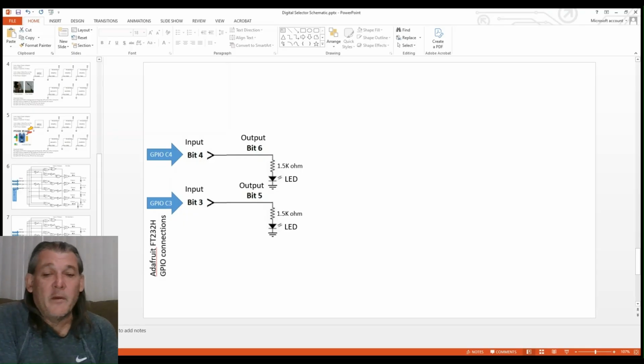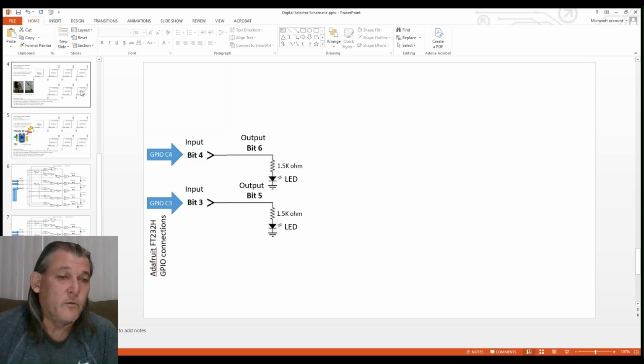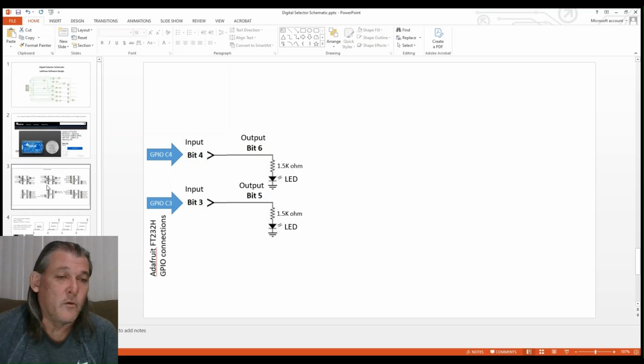And that's basically the pinout in the schematic of this board, so you can build it if you want to. But I warn you to use a fuse, and you use a fuse that's smaller than what your power supply supplies. That's something someone had warned me about before.